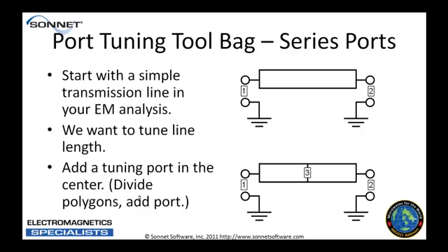Let's talk first about series ports. Imagine a hypothetical exercise here where we start with a simple transmission line in an EM simulator. We want to tune the length of this transmission line, so what we do is we take our little ideal X-Acto knife, we slice that transmission line through the middle and add a tuning port in the middle. So that's basically a series port now that we've introduced into the transmission line in the EM simulator.